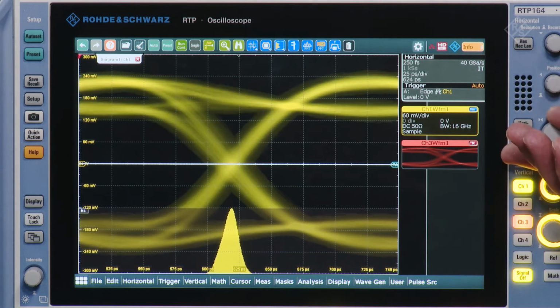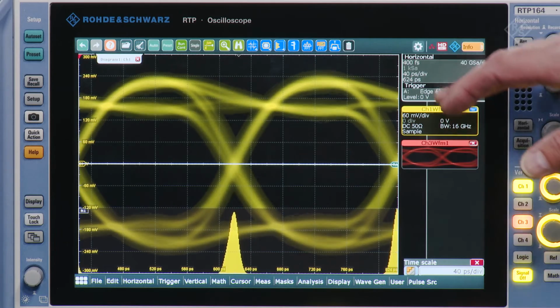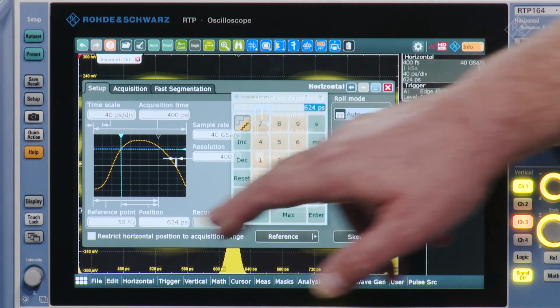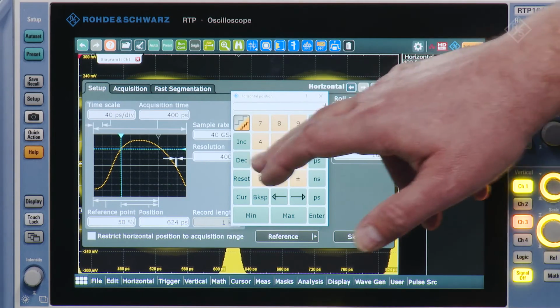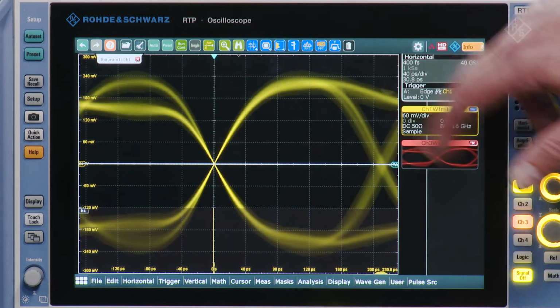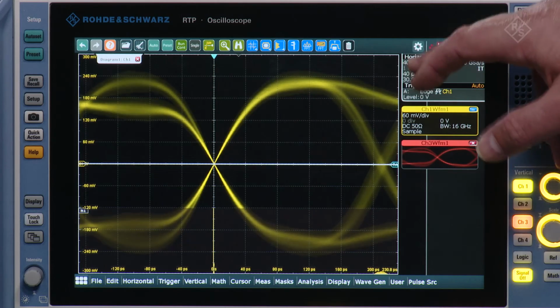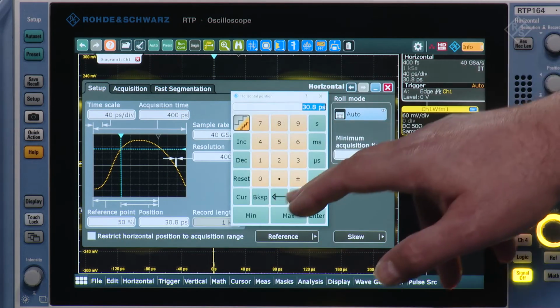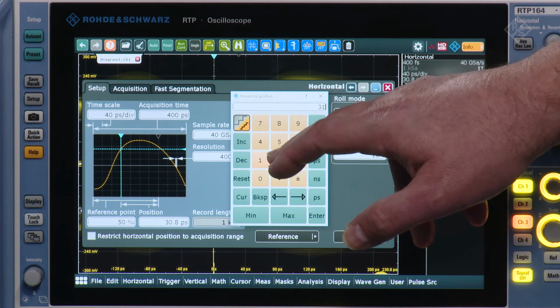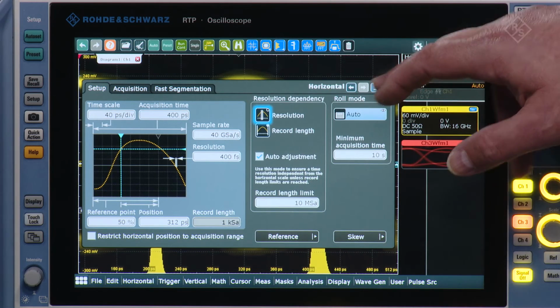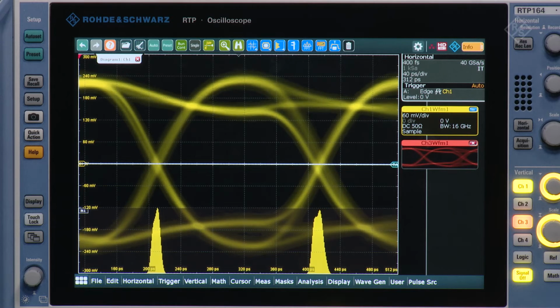So this one eye, I can change it a little bit and shift it. This is a trigger point, and the trigger will basically remove the jitter, so this is not suited. I need to shift it a little bit more. So I shifted it now about 2 UIs further down. Now I see 2 histograms for each crossing one. Unfortunately, they're not the same.